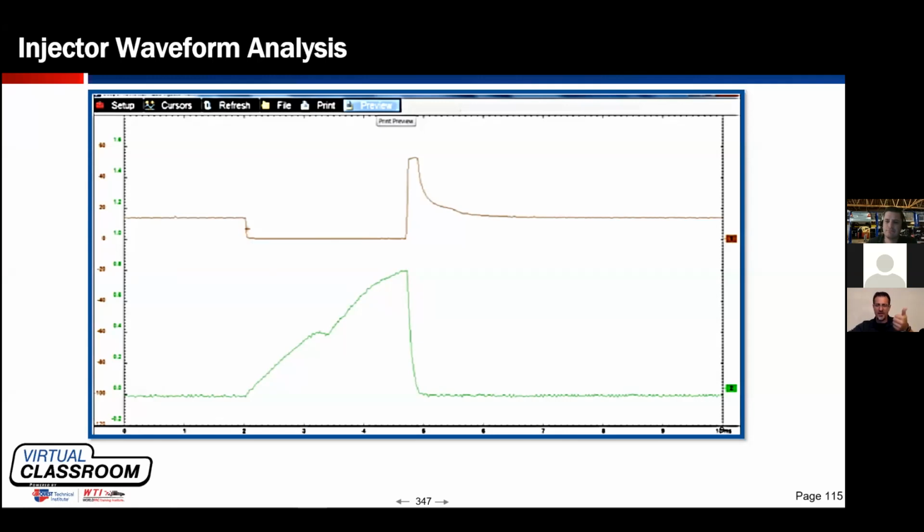So I don't have an engine mechanical problem. I don't think I have an ignition problem. And I don't think I have a fueling problem. What did we miss? So Dave reflected upon the tests he did perform, and he said, I can conclusively eliminate fuel by way of fuel trim, the injector voltage trace, and current trace, along with the pintle bump. It's not fuel. He can prove it's not spark.